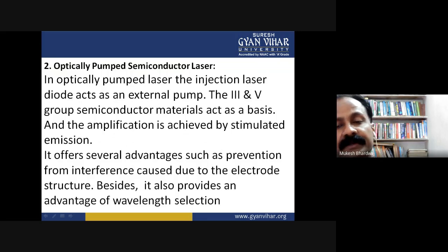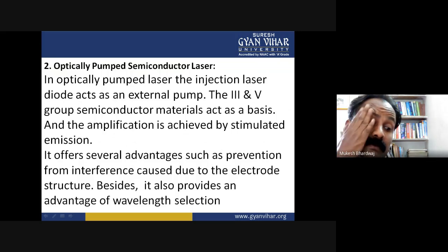And the optical resonator, which is essential, consists of two mirrors facing each other. The active medium is enclosed by this cavity. One of the mirrors is fully reflective while the other mirror is partially transparent. The optical cavity makes stimulated emission possible in a larger number of atoms in the active medium. This naturally increases the intensity of the laser beam.